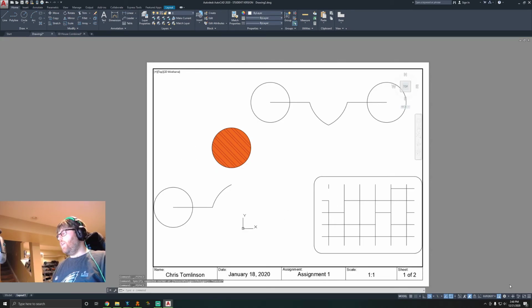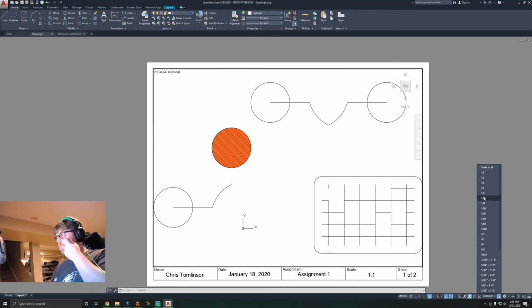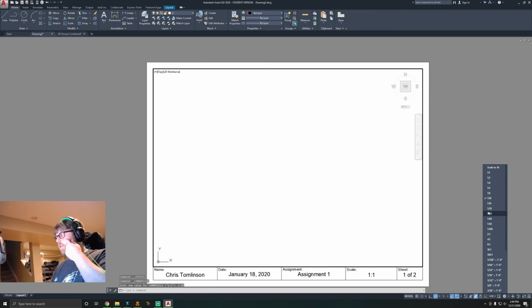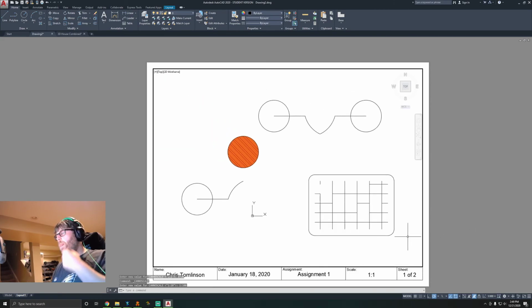If we double click here, right now this is our scale, this 0.012 and so on, and that's saying 0.012 to 1. So it's approximately a 1 to 100 scale; sorry, maths. We want to get this to an appropriate scale to display it, because people can understand 1 to 100.